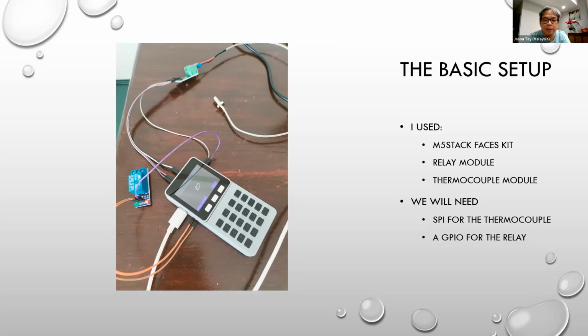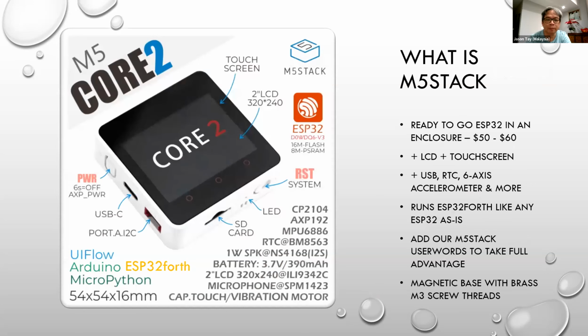And then finally, we need a relay to control power to the heater. The relay pretty much sits on a GPIO. You can think of it as an LED, a very slow LED, because as we'll find out, we can't blink this LED very quickly. There are multiple ways to get that done, either through what they call bang-bang control of the temperature, or else PID. But the emphasis today is we're going to go through what it took to add M5 stack support to it.